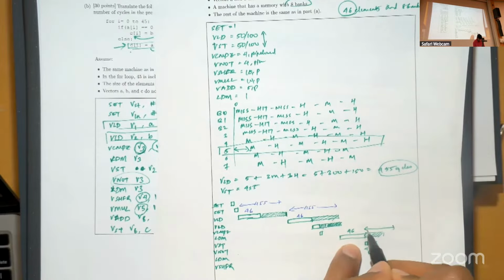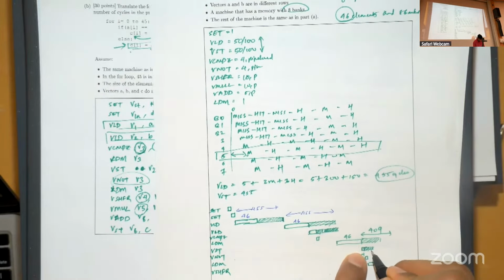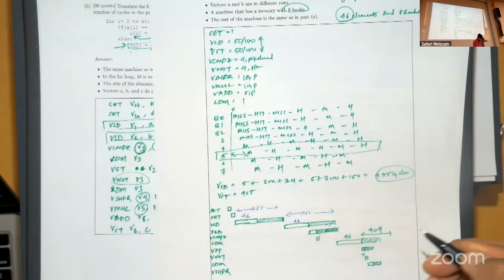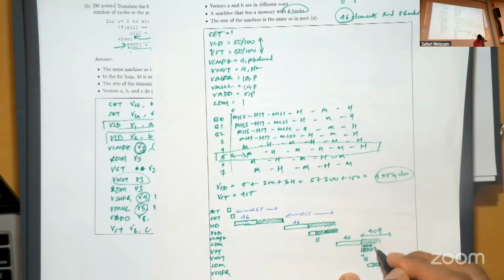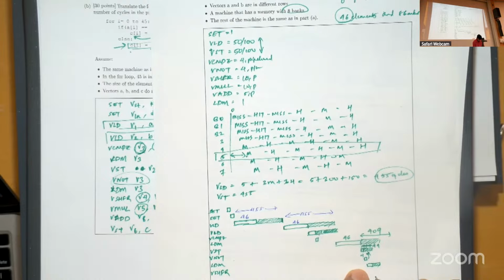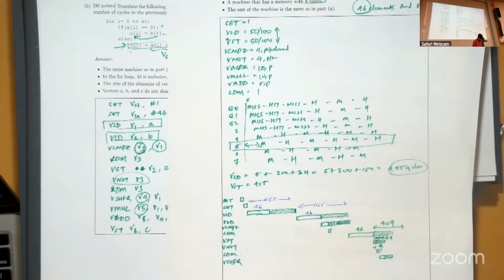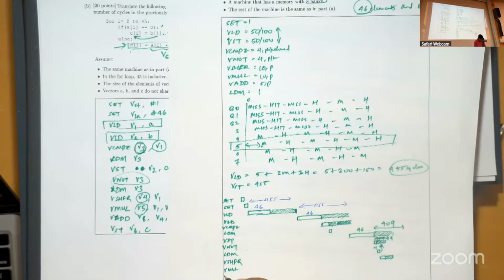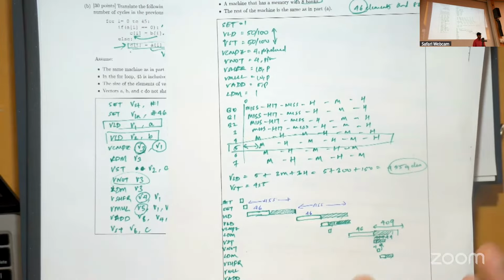This is about 455 minus 46. Let's say this is 409 cycles. vNot would take 4 pipelined, which means around 4 plus 45. This would be 49 cycles. This is hidden behind the vNot, so we don't need to worry about it. vShiftWrite is also going to be mostly hidden behind the vNot. Again, we don't go beyond the 409 cycles, essentially. That's what I'm trying to convey here. vmul, vadd are similarly going to be hidden behind this portion because 409 is very long anyway.